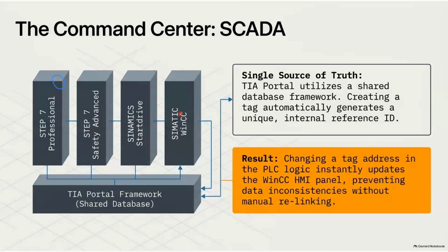For these 22 IOs, when coming to development of this SCADA, we have to give 22 tags, and not just 22 tags. If it is a tank and it keeps filling, then we have to provide the water level indicator. For that water level indicator, again, we have to give a tag, name it appropriately, and assign the IO.